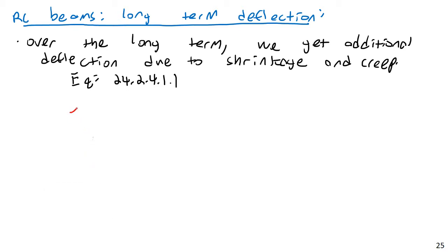Lambda delta is, and the equation for this is going to be xi, the Greek letter there. And so it's going to be our squiggle here. Basically, all we're going to do is have a simple formula to calculate this. Of course, we're going to get our initial deflection based off of everything we've learned previously. So, in other words, you'll be using the method of transformed sections, all that sort of thing, to find the overall final deflection.